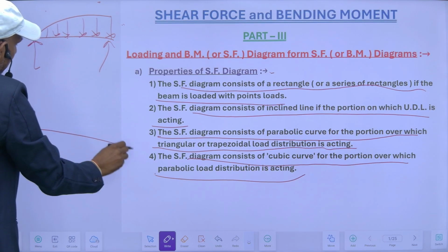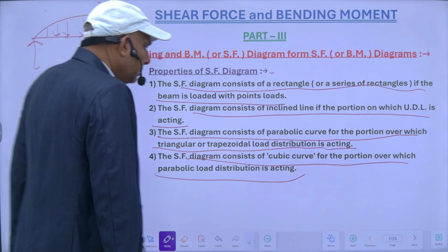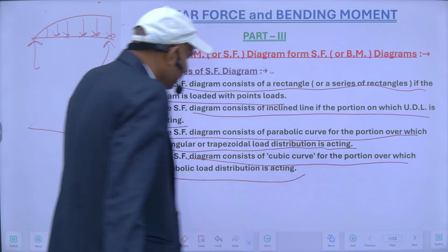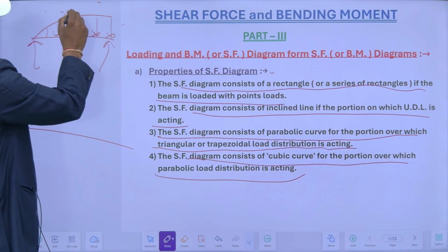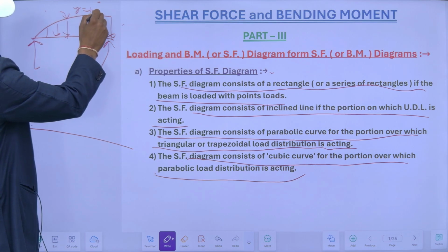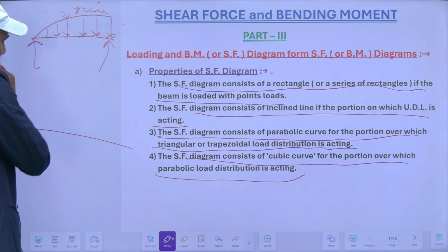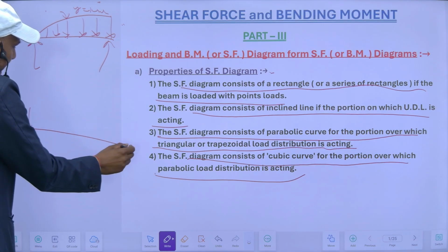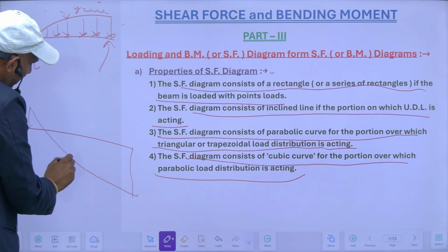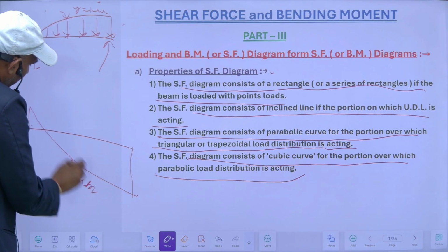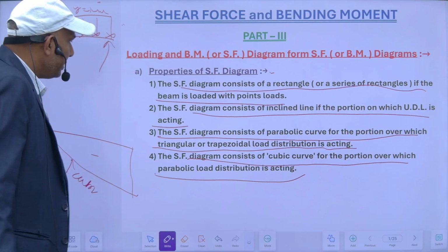So in this case, my shear force will be a cubic curve on this parabolic load. So it is y is equal to kx square. So in this case, it will be a cubic parabola. So this is for shear force.